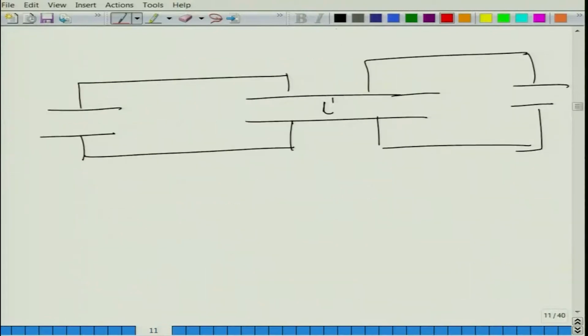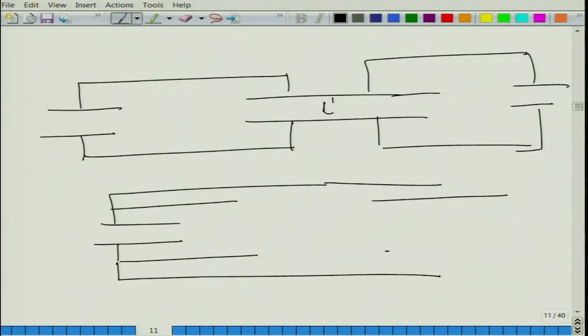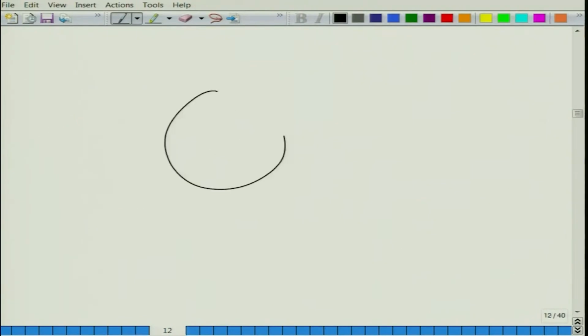And another thing that you can also do using this mode matching is a folded resonator concept. So, that is something like this. There is resonator L1 here, L2 here, the length is like this, L3, L4. So, one can do lots of things with this analytical mode matching, provided that it is concentric circular. If it is not concentric circular, if you have an eccentric annular, something like this, then unfortunately this Bessel, then this can actually be used to analyze a simple expansion chamber, that kind of a thing.